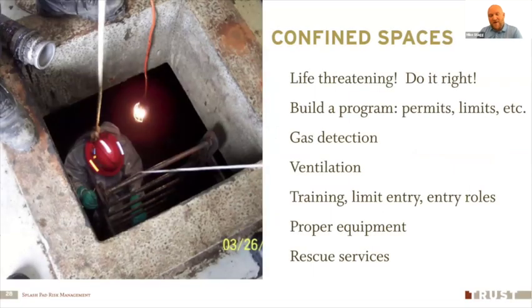So you got to have a program around confined spaces, permits and limits and things like that. Got to use your meters, gas detection and ventilation and training. Proper equipment and rescue services have to be in place if you're going to go into your confined spaces.